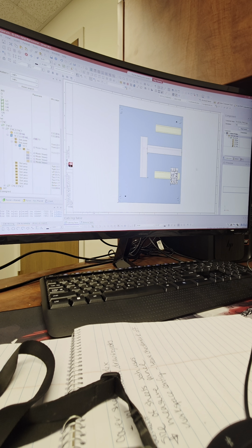Okay. So what I would do is, you would definitely need a duct above your rail and one duct below your bottom rail, because you have some wires that are kind of wrapping themselves around. All right, so we need that one, and one over all the way on the top. Top one is going to be tight.